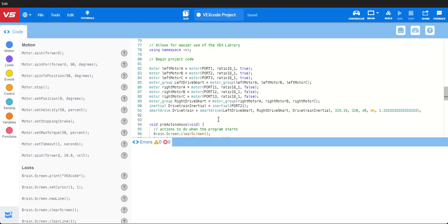I would recommend to test this, that you pick your robot off the floor so the wheels aren't touching, and then test each of these ports one at a time. So unplug 2 of them, ports 2 and 3, and have only port 1 plugged in. And then test with your code writing, test the joystick to make sure that when you push the joystick forward, the left side of the drivetrain spins in the direction you expect it to. Then unplug port 1, plug in port 2, test the same thing again, and then repeat with port 3. What you can do here is make sure that each motor does properly drive the drivetrain.